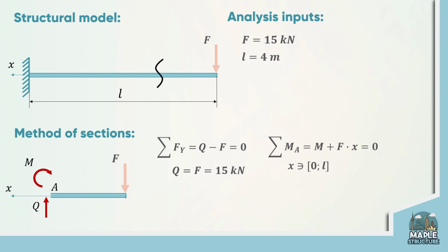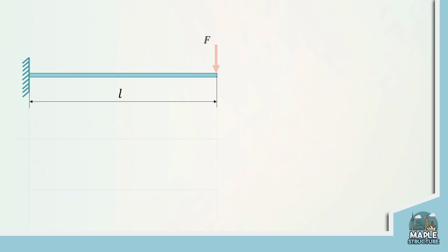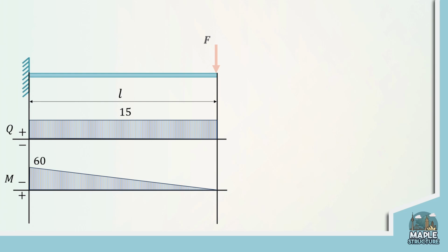The start point, where x equals 0, is the right end of the beam, so I suggest we take the x equals 0 point and put it into the equation, and x equals the full length of the beam, and plot the diagram. So we just have to connect these 2 points with a straight line. So no extra words, you can see those diagrams on the screen with all values of shear forces and bending moments we determined before. And on that positive note, I'll wrap things up.